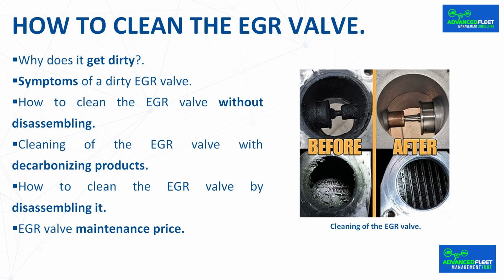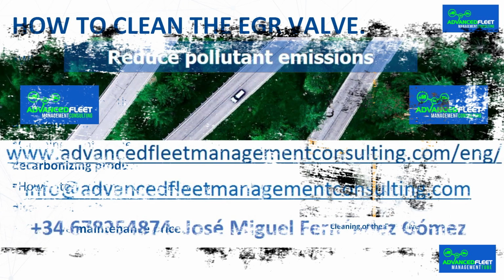Keeping the EGR valve clean is essential for good performance and efficiency of the car's engine. Depending on the severity of the blockage, you can opt for cleaning methods without disassembly or, if necessary, perform a complete disassembly for a thorough cleaning.